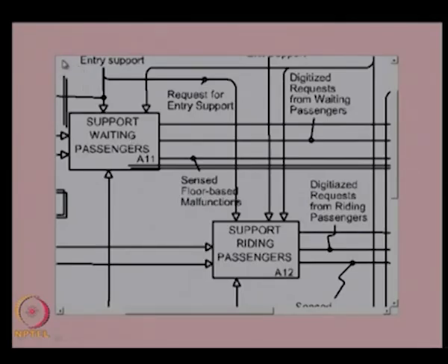We go through each input and find out all the functions through which it passes and try to find out whether that function is really capable of transferring the input to output, or whether there is any overlap of function which is redundant in transferring the input to output. That can be done through this diagram. So we go through each and every function through which the signal passes and finally identify all the functions which correspond to that signal and then look for any shortfall or overlap.